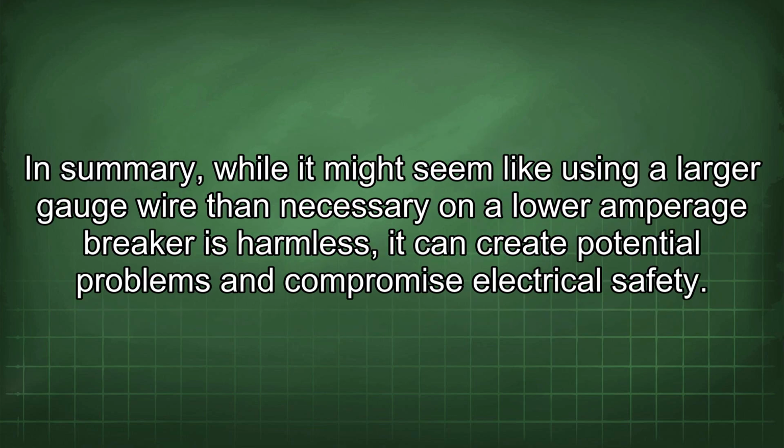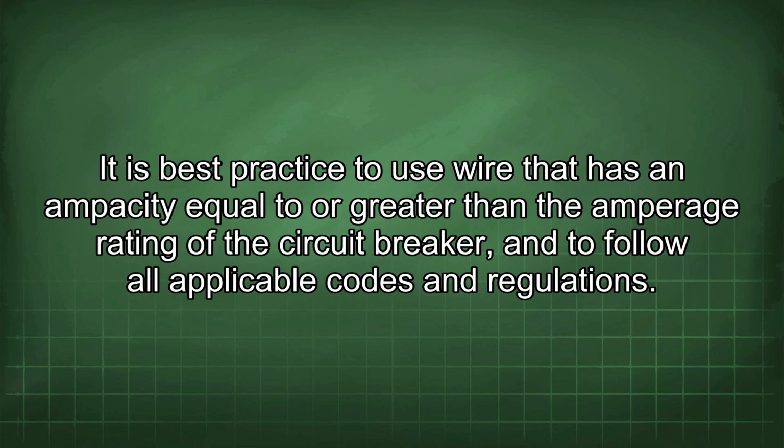In summary, while it might seem like using a larger gauge wire than necessary on a lower amperage breaker is harmless, it can create potential problems and compromise electrical safety. It is best practice to use wire that has an ampacity equal to or greater than the amperage rating of the circuit breaker, and to follow all applicable codes and regulations.